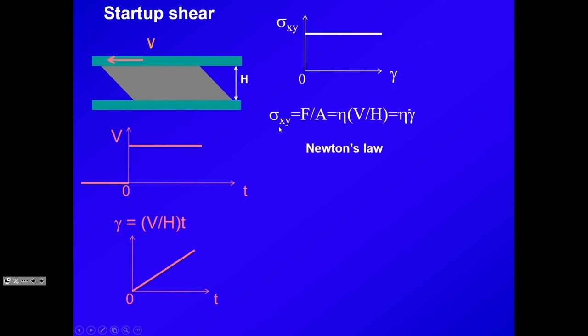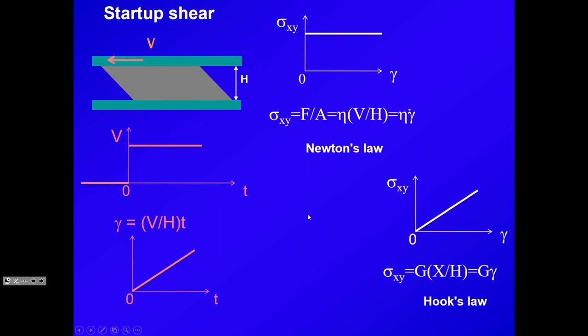If you claim your material to be viscoelastic, number one. Number two, if you claim to have good enough time resolution, for example, capturing the stress, the force you can sense, on time scales much shorter than your internal relaxation time, tau, if you can do that, then I claim you will never see what I just showed you here. It will always be like this.